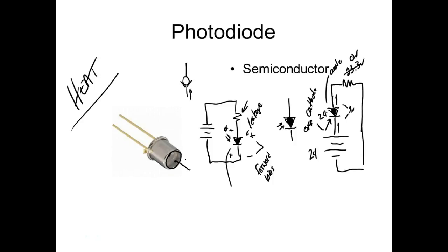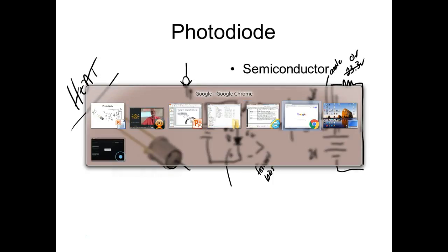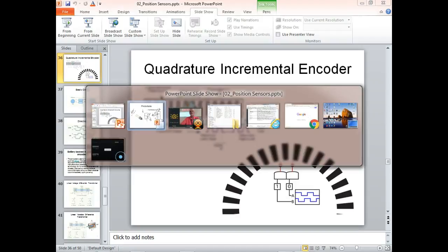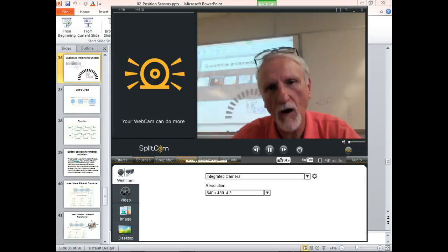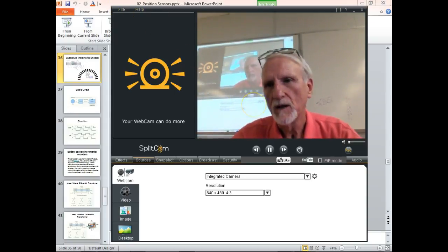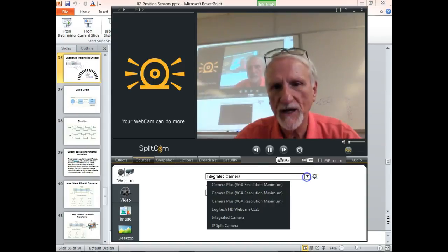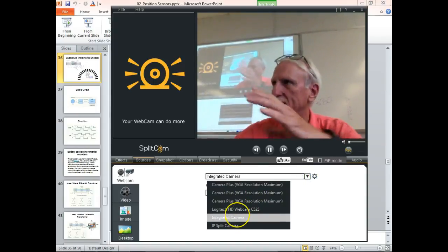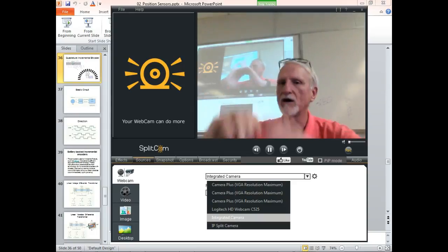This would let us focus the light on that encoder that I've got around. Those use photodiodes. You can tell they're photodiodes because they've only got two lenses to them. These are going to pick up light over a viewable angle. The one that I have a picture for is going to pick up the light when it's pointed at it, because it's got a shield that comes on the outside, right? Does that make sense?